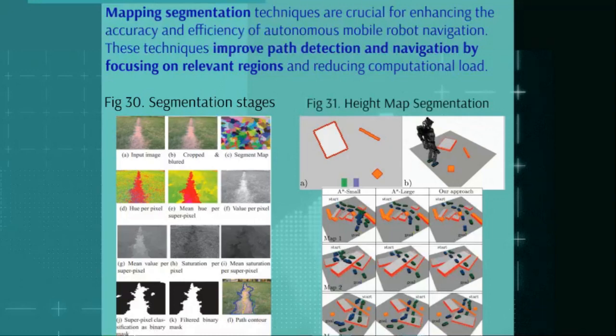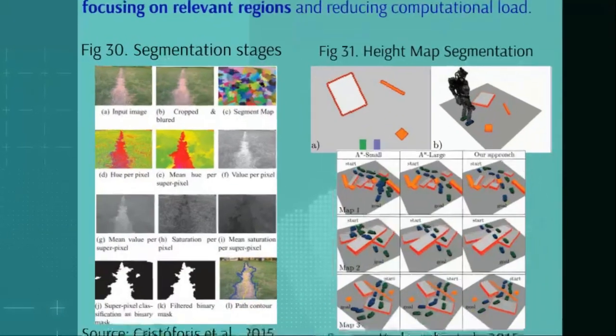This height is converted using transformation in inverse kinematics, so the robot understands that it needs to move its legs upwards to overcome these obstacles, step over them, and finally traverse them. If the area is a plane, this gray plane, the robot just moves normally without stepping over anything, and that's the idea of segmentation. So we show different applications here.